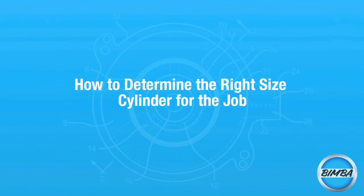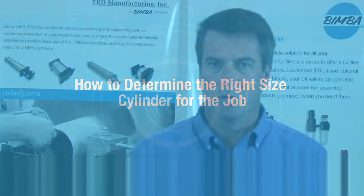To determine what size cylinder the task requires, you need to answer 3 key questions: load, velocity, and air pressure. How heavy is the load to be moved? Set by machine design. In order to move the load, you need to choose a cylinder that provides force greater than the load. It's a good idea to allow an additional factor of 25% force overload to